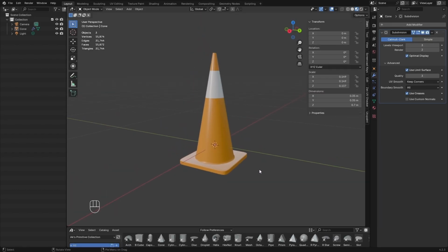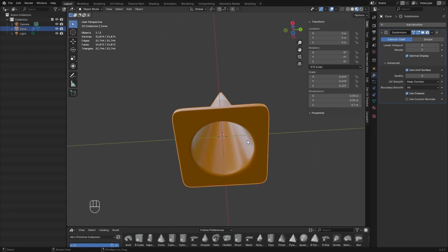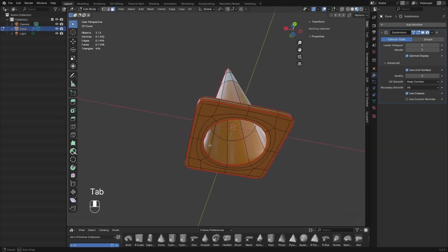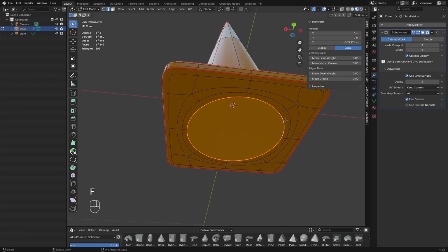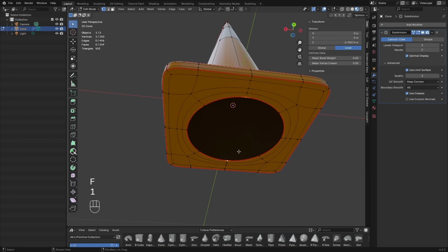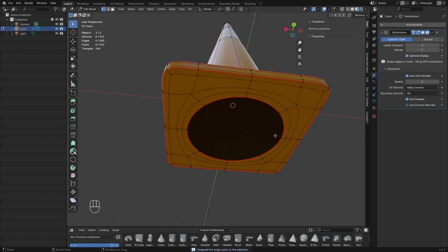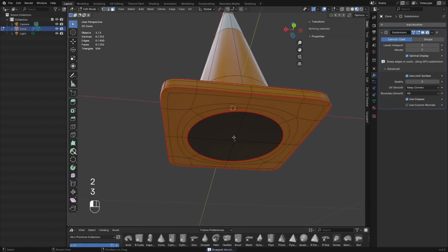The next thing we are going to do is reposition the origin of the object. So what I'm going to do is create a temporary face. So I'll select the edge there and just fill it in, and then I'll split the face so that I can select the vertex in the middle and set our origin to the selection. And once that's done, we've got the origin right at the bottom of our object there, and I'll get rid of that temporary face that I've created there.